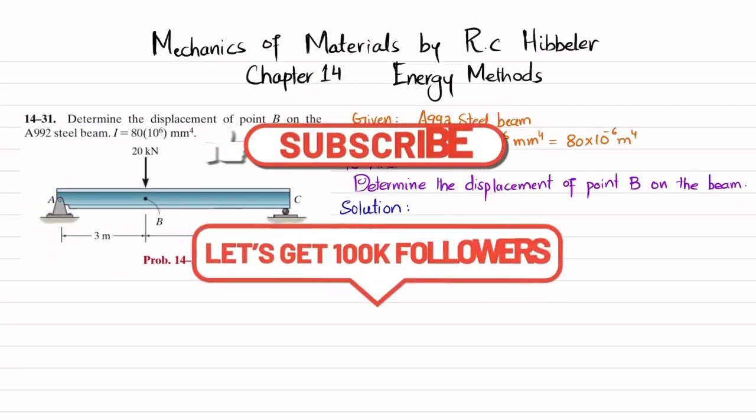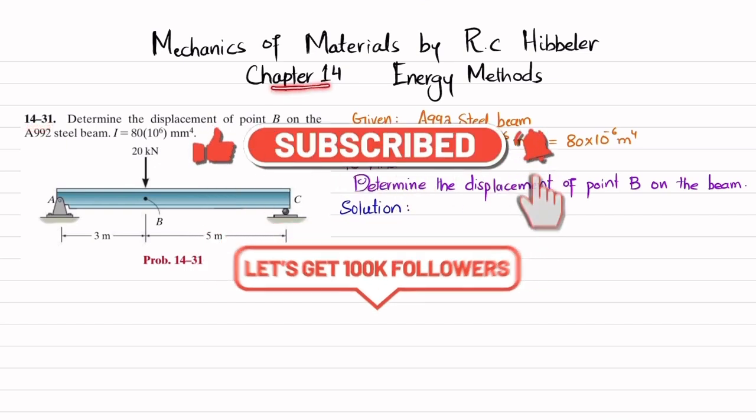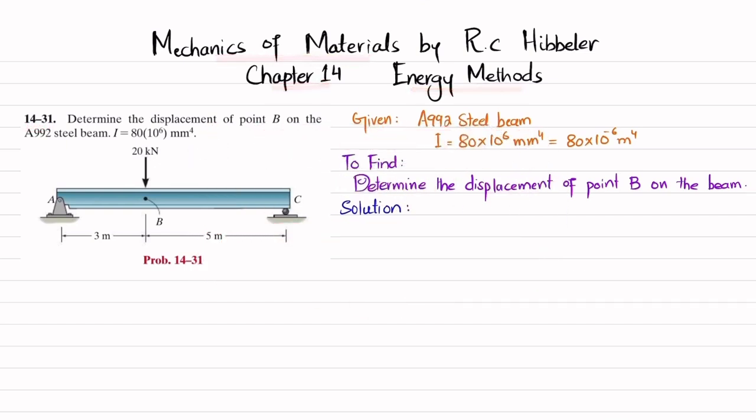Welcome back. In this video, we are going to solve problem 14-31 that is taken from chapter number 14, Energy Methods, and the book name is Mechanics of Materials by R.C. Hibbeler. The statement is: determine the displacement of point B on the A992 steel beam. I is 80 into 10 to the power 6 millimeter to the power 4.